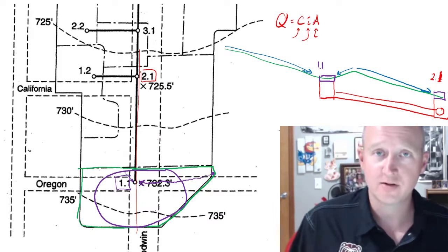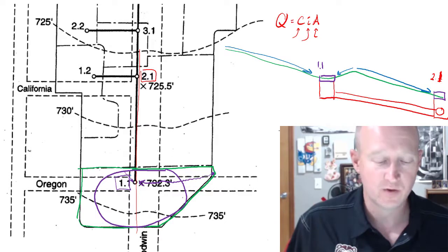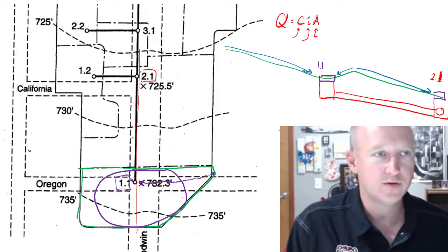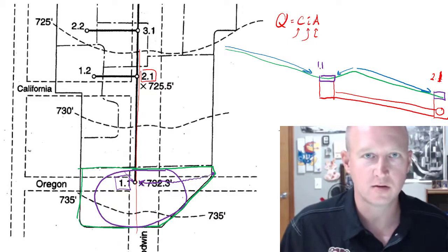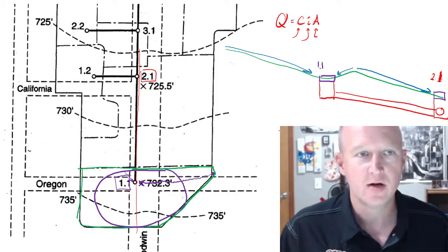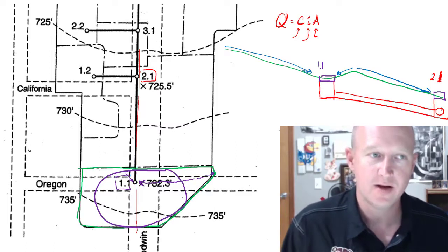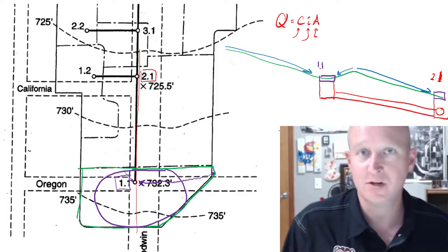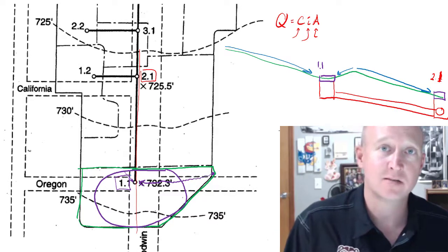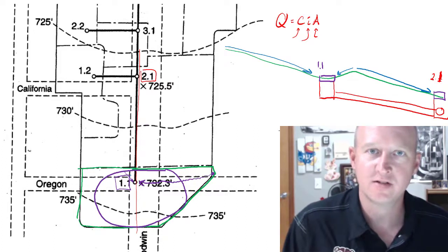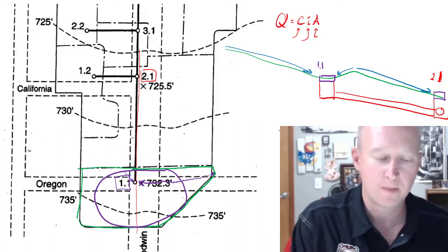So the bigger area is going to produce more runoff, right? So we want to make sure that we're draining the entire area. If we used a duration storm that was longer than the time of concentration, then that would drain the entire area. The entire area would be contributing runoff, but the intensity of the storm would be less than the maximum intensity. So we know that as storms get longer and longer in duration, their intensity is less. And so we want to use the greatest intensity that corresponds with our site.